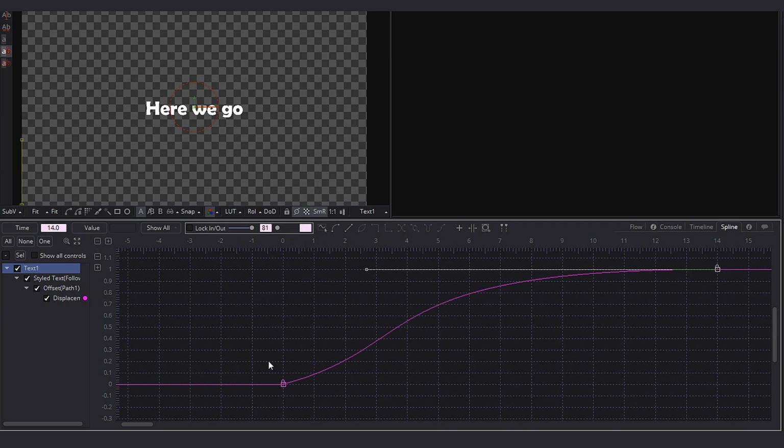So to show how that works, I'll select this keyframe, set it to F and increase this value. The right handle is moving. I don't need this, by the way, so I'll just Ctrl Z to undo all that. Another tip, we can move these handles horizontally or vertically by holding Alt. So if I hit Alt on the keyboard and move horizontally, we'll get perfectly horizontal movements. Or if I hit Alt again and start moving vertically, I can get perfect vertical movements.